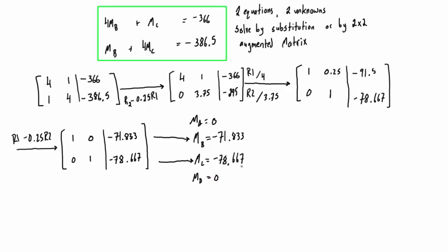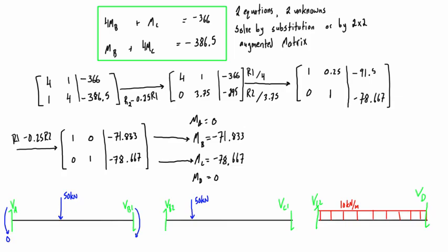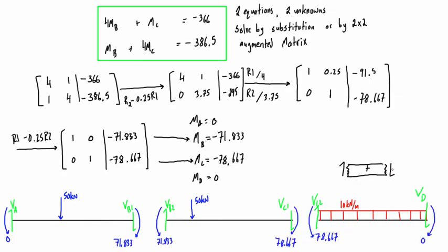Okay, so now what we want to do is draw the actual free body diagram of each span with its applied loads and internal moments and internal shears, basically sectioned just right before the supports. So when I do this, I draw on the shears in the positive senses, and they're all unknown values, matching the positive sign convention for beam bending.